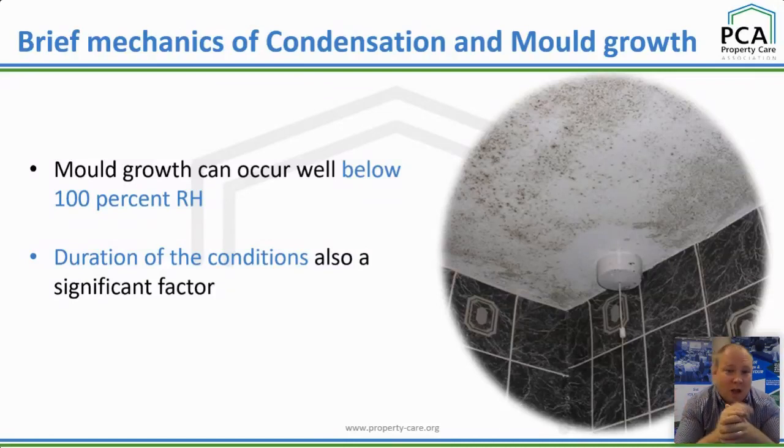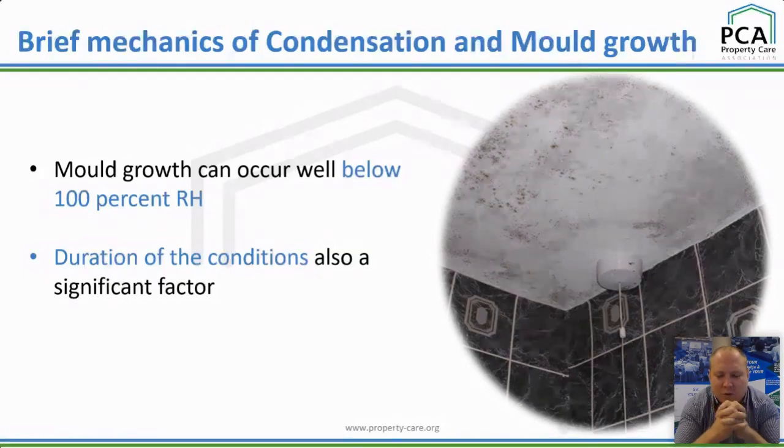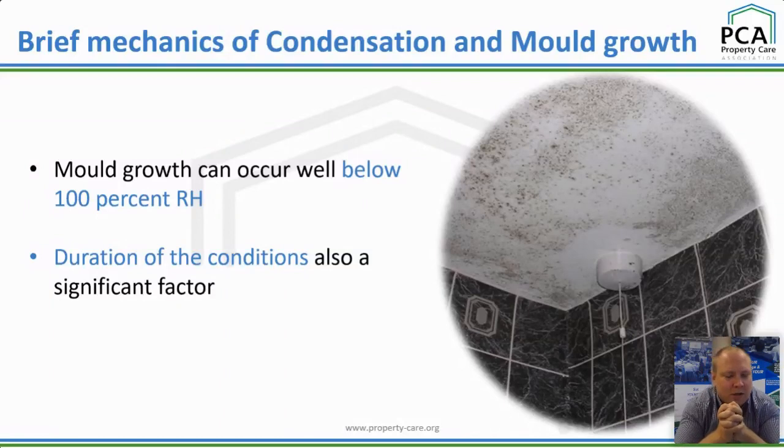And I personally feel that when you've got severe condensation and lots of liquid water on the wall, that actually makes the conditions too adverse for mold growth. When you see liquid water running down the walls in the corners of rooms, I think the conditions there are too wet for mold growth to occur. That's more of a personal hypothesis than anything else, but when you think about it, that seems to be the case.